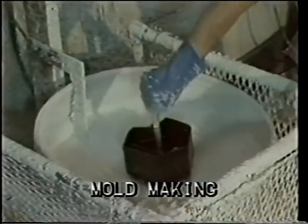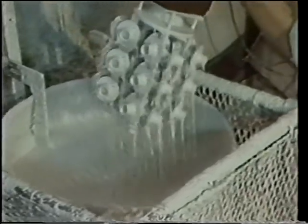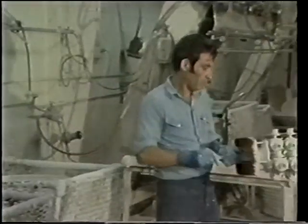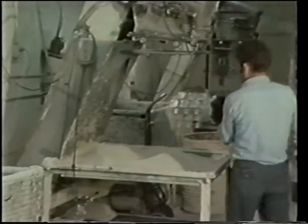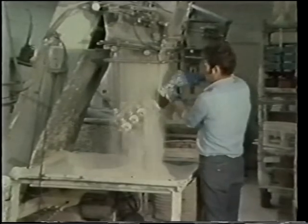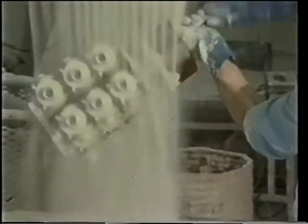The cluster is coated with a ceramic material which has great heat-resistant properties, called refractory. A first or prime coat acts as a base for the mold and must withstand attack by the molten metal. Here, the fine refractory is suspended in a liquid binder, or slurry. The slurry-coated cluster is then stuccoed with a coarser, dry refractory. This adds strength to the initial coat and prevents cracking of the mold by retarding shrinkage during drying.